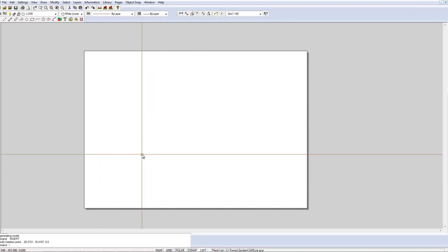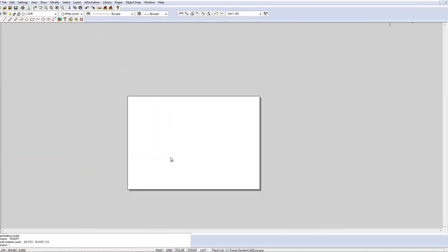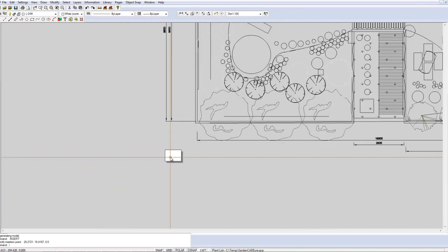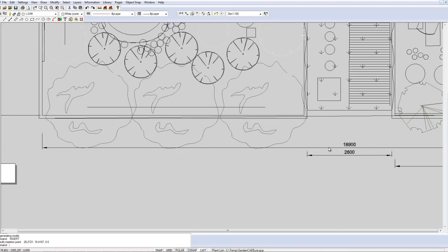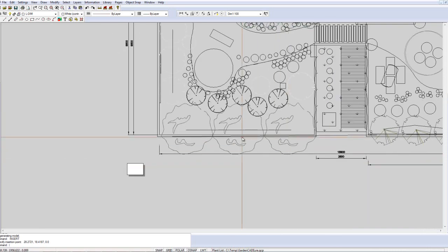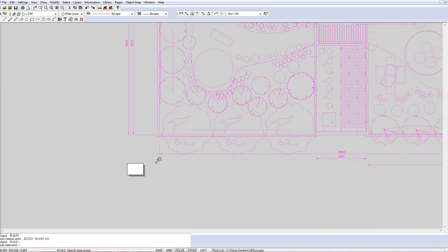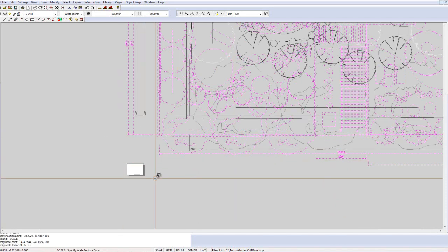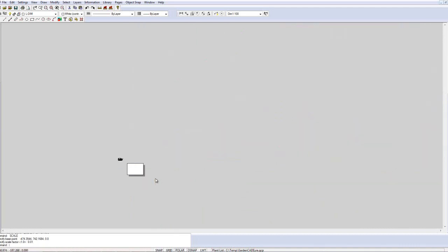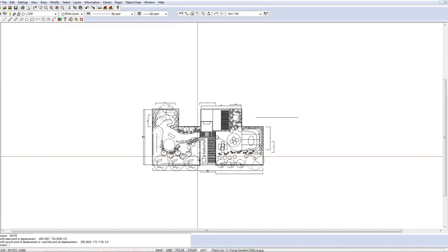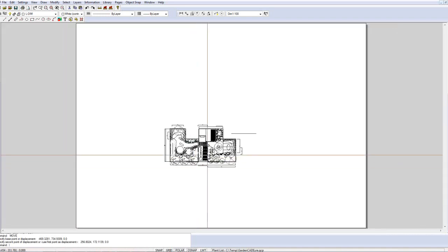So I'll just click. Now when we right click and zoom extents, we should be able to see, and I've got to come right out here. Here's our fully accurately dimensioned block, and it's just now a matter of scaling that down. We could scale that by 0.01, so that's a 1 to 100 scale, and then we can pick that block and move that block onto the drawing sheet. If we then zoom extents, you can see it. So clearly we could scale that up again.